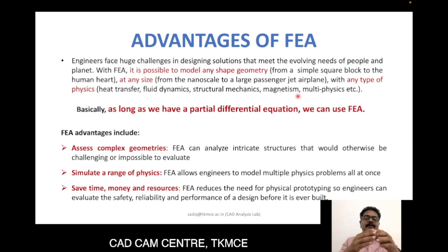The seal will have to flare when there is a force, and the force comes from the fluid in the shock absorber. So the fluid force problem and the mechanical structural problem of the rubber have to be connected to explain the working of that. Those kinds of things are all called multi-physics problems that go across various domains. Those can all be done by using finite element analysis.